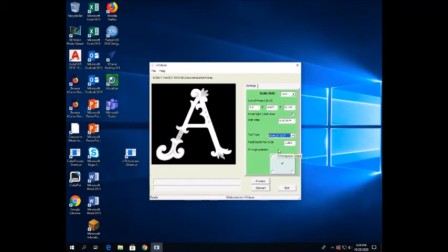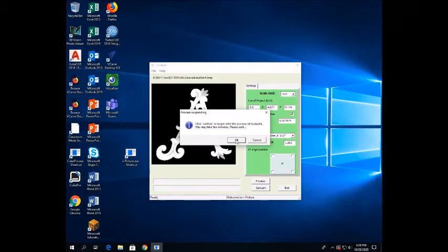So we're going to look at a preview of this piece. Again, I have it inverted, so the light areas of the A should be the deepest. Here it's showing you where the origin of your tool would be. This is the left side, but I'm going to stick with the center origin. Therefore, when I set up the machine on the CNC, I know that my start point will be the center of my project, so that I can measure my border around.